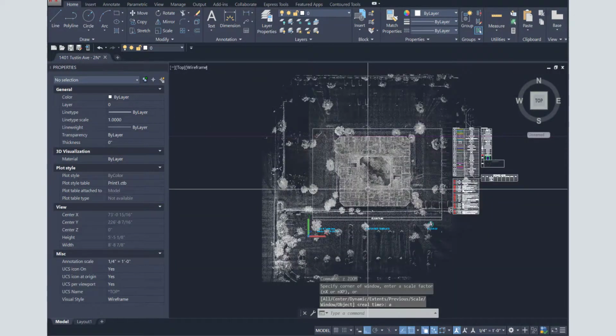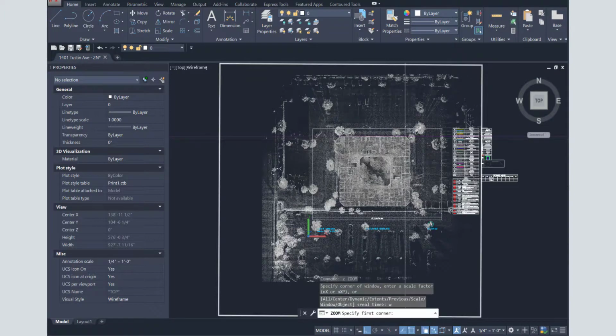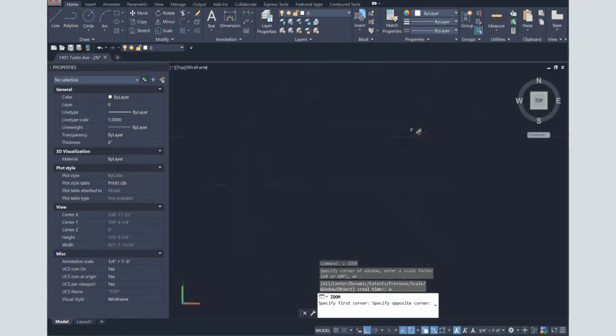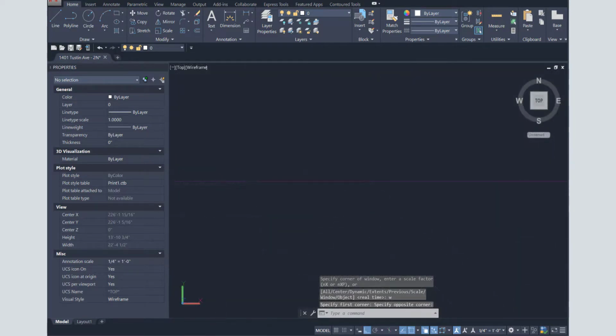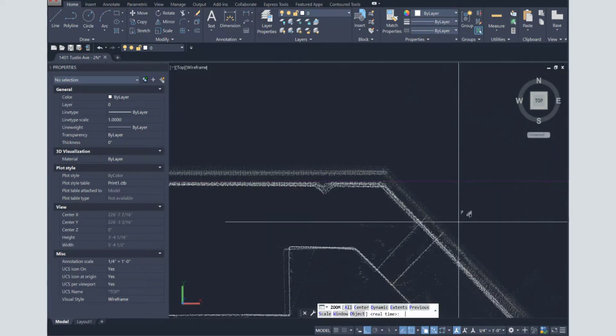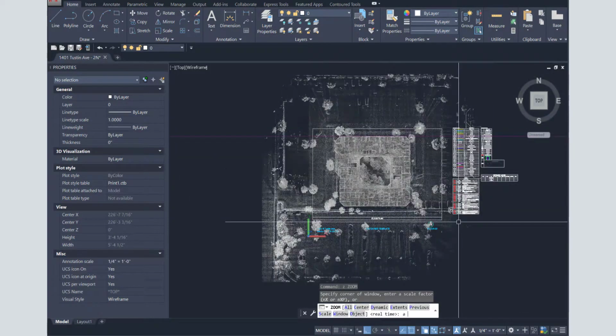Verifying the rotation of the point cloud is as easy as drawing a horizontal X-line and a vertical X-line along some of the longer walls of the building. You'll want to check a few to make sure everything is good to go. Taking your time on this step is very important, as this sets up the rest of the building to be as nominal as possible.